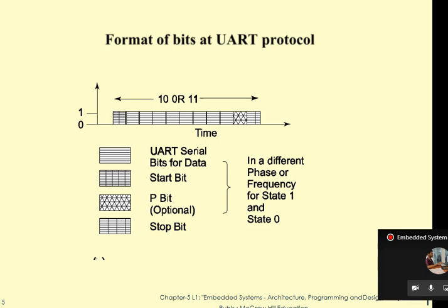If you see here, the first one is nothing but your start bit. Can you see this? Yes, sir. So that is the start bit that I am representing here. So always while initiating any communication, or initiating to transfer the data, first I will send the start bit. Along with that start bit, I will send the 8-bit data, 1, 2, 3, 4, 5, 6, 7, 8. So this 8 is nothing but the data.